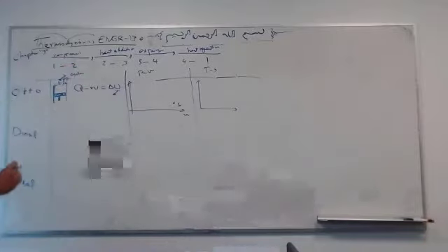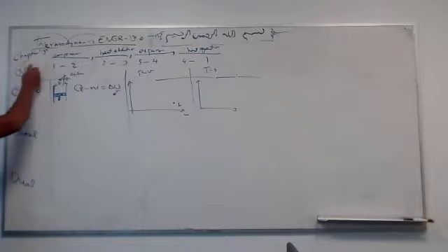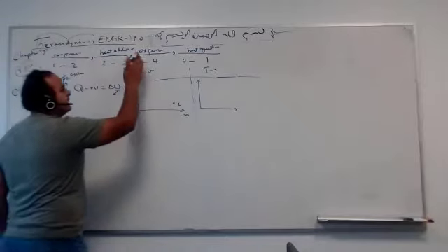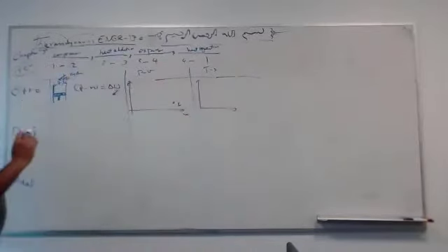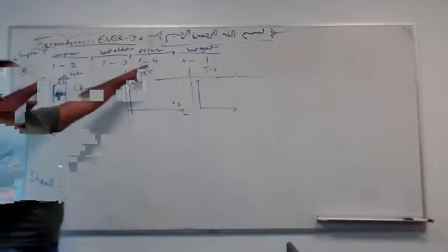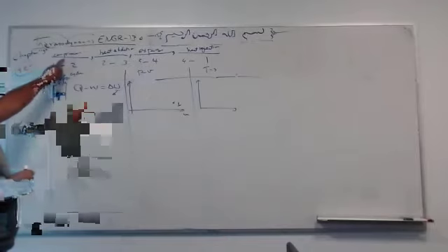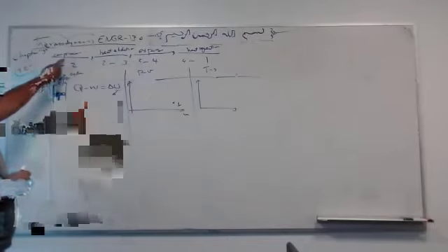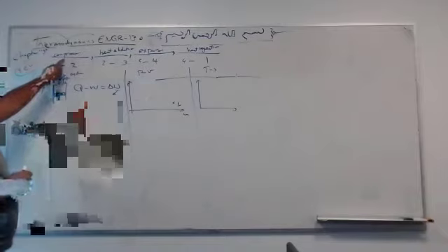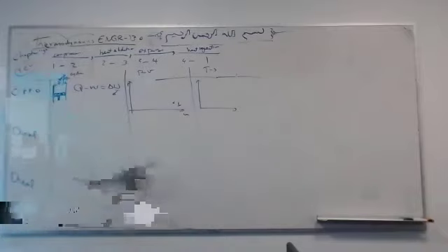Here, in this compression, everything is reversible. Compression, heat addition, expansion, all of them are reversible. It means the most ideal process. I can reverse it without changing the surroundings. This is called reversible. Now, this is reversible and adiabatic. So when you hear the words reversible and adiabatic, it means what, guys? Isentropic. Perfect.